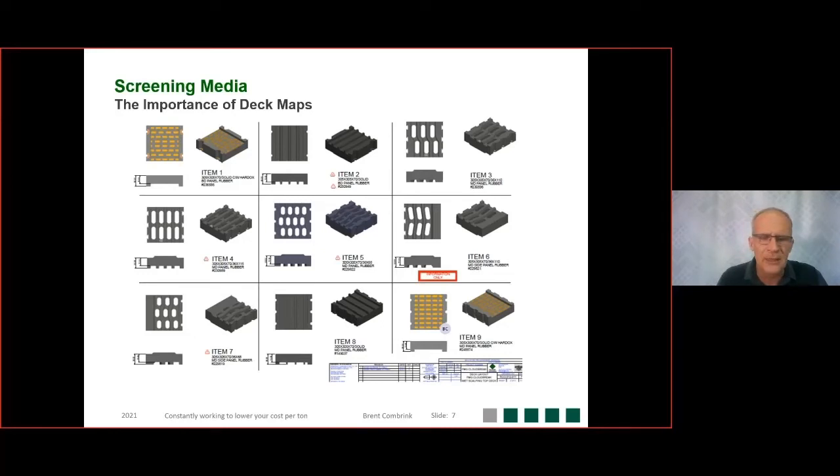Another example, and this ties in with Gulf's presentation as well in terms of field maintenance. The impact panels on a screen, they also had problems with the specific area because a wet scrubber was feeding 300mm material with a drop of 3 meters. So obviously you're going to have excessive wear on the feed area, especially if it's iron ore.